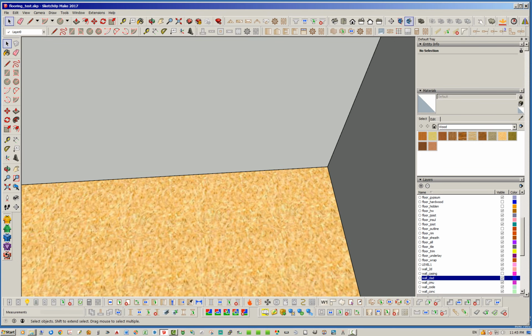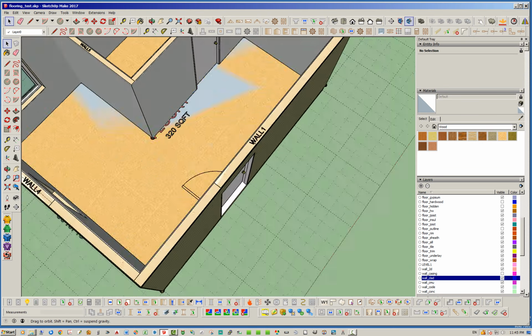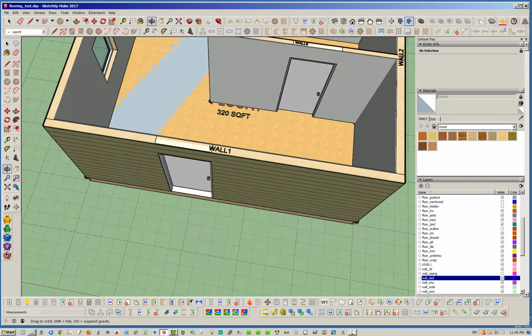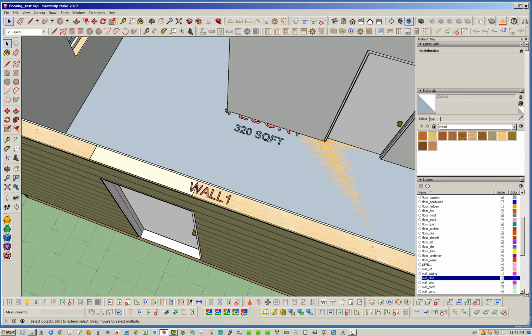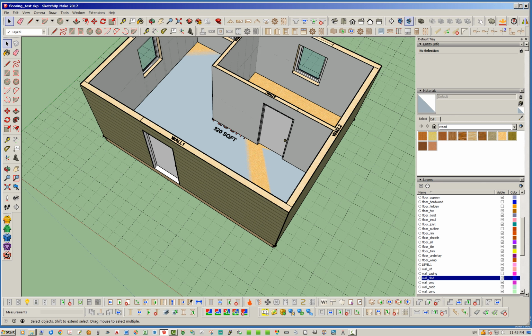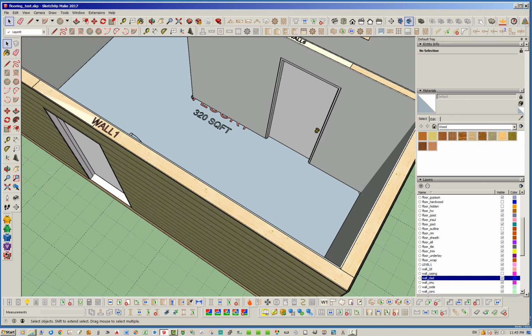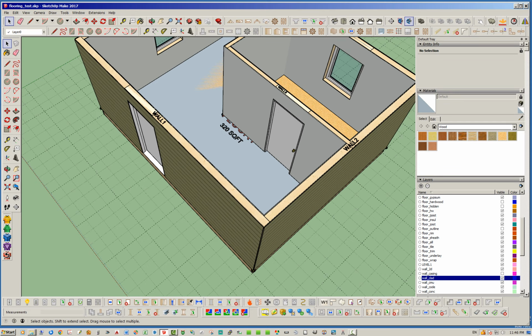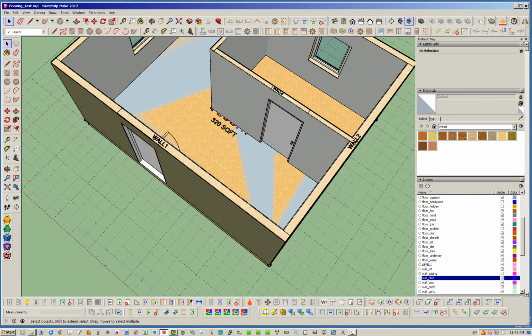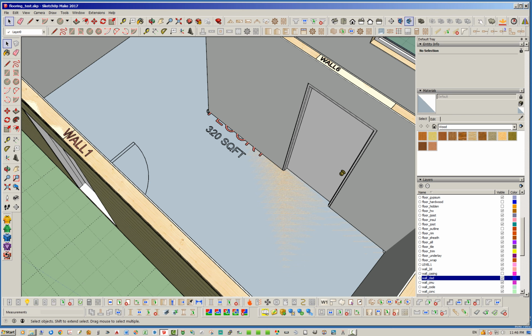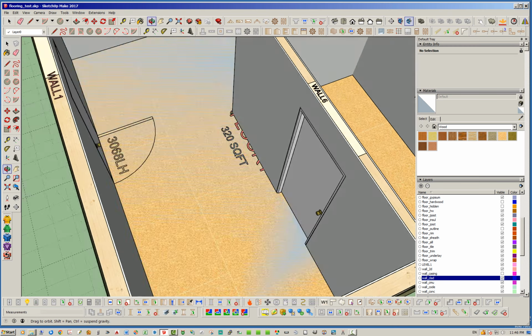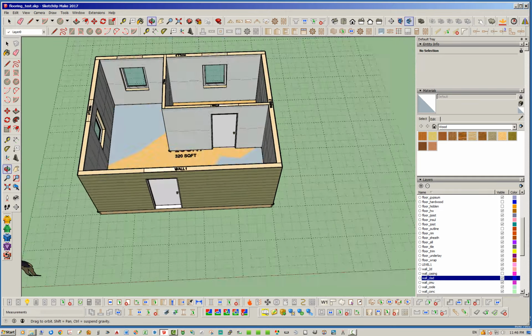Okay, and as you can see, we've got a little Z fighting there, which is what we'd expect. So that face is right on the face of the floor, which is exactly where we want it. One thing to note is that when you place your flooring, it will place it within the floor assembly itself, and the Z height will not necessarily be on the top of the sheathing. I mean, it should be, but it's not actually looking for that. It's going to put it wherever you create that face. So if you lift that face up a half inch or whatever above the sheathing height, it will place it a half inch high. Okay, so we've got ourselves a face.